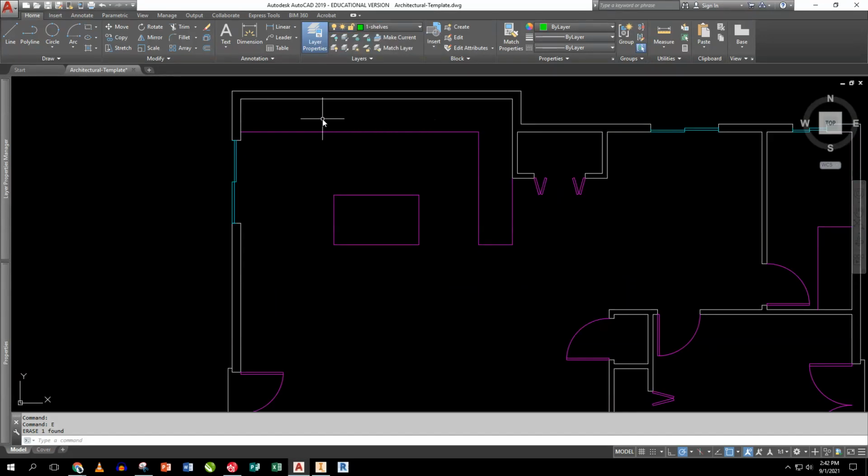Now, shelves, I can literally do this. Line from here to here for my upper cabinets. If I mounted them on the wall, and I would move the previous, which is just, okay, so I'm going to M, and then I can hit P for previous or L for last. Hit the enter key one more time because I'm done selecting. Pick a spot to grab and just drag it out straight down 12 inches. That's an upper cabinet.